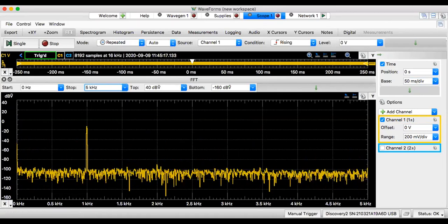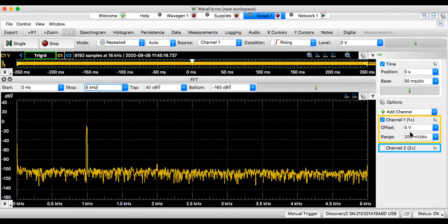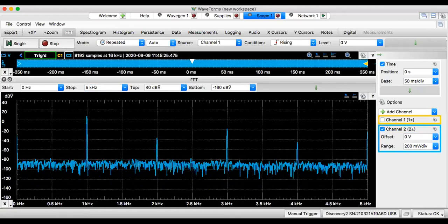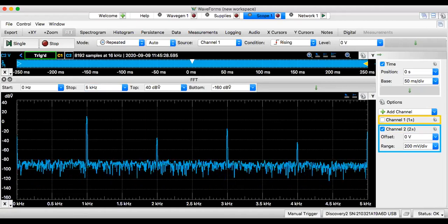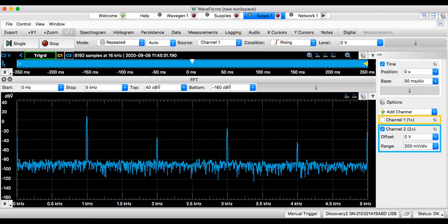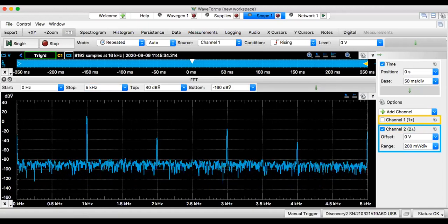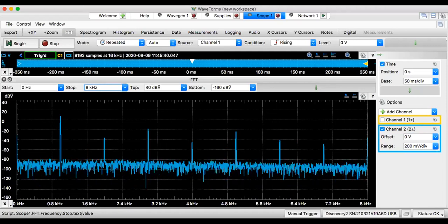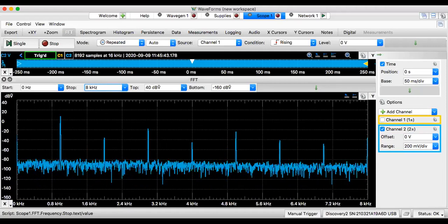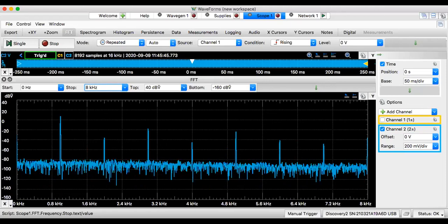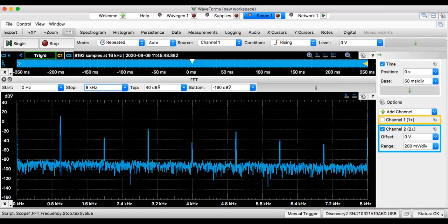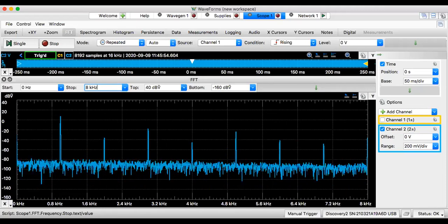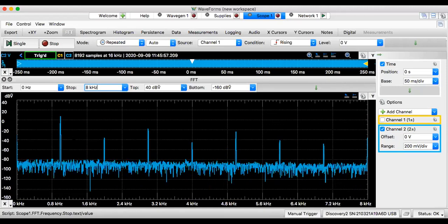The distortion will be a little bit better, but it still has distortion. So let's look at my harmonic distortions. Yeah, 1000, 2000, that's called a harmonic. This is called the second order harmonic, third order harmonic, fourth order harmonic. Let's keep looking. This one is called the base, the original, 1000. The second order harmonic is not supposed to be there. In an ideal amplifier, the output should only have 1000 hertz. That's in the ideal world.